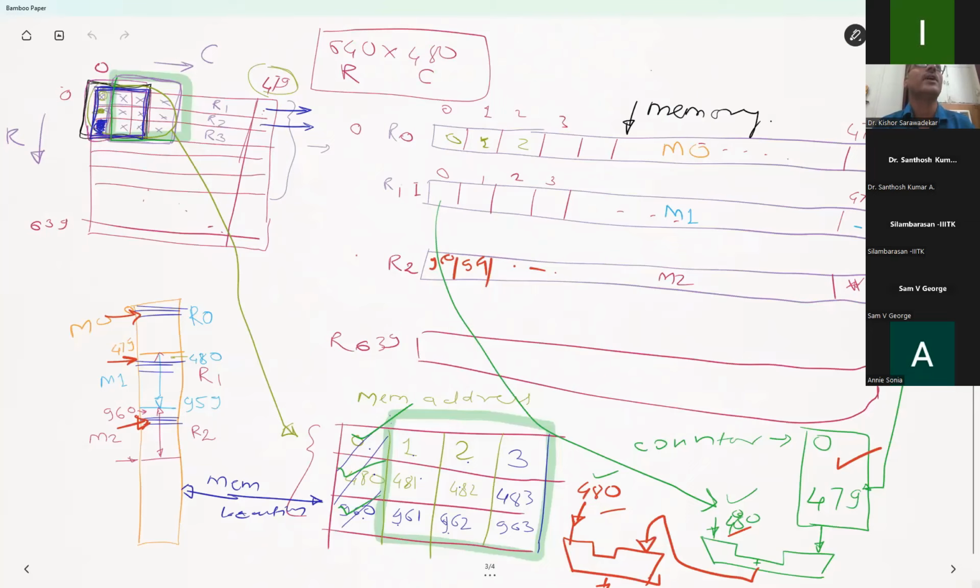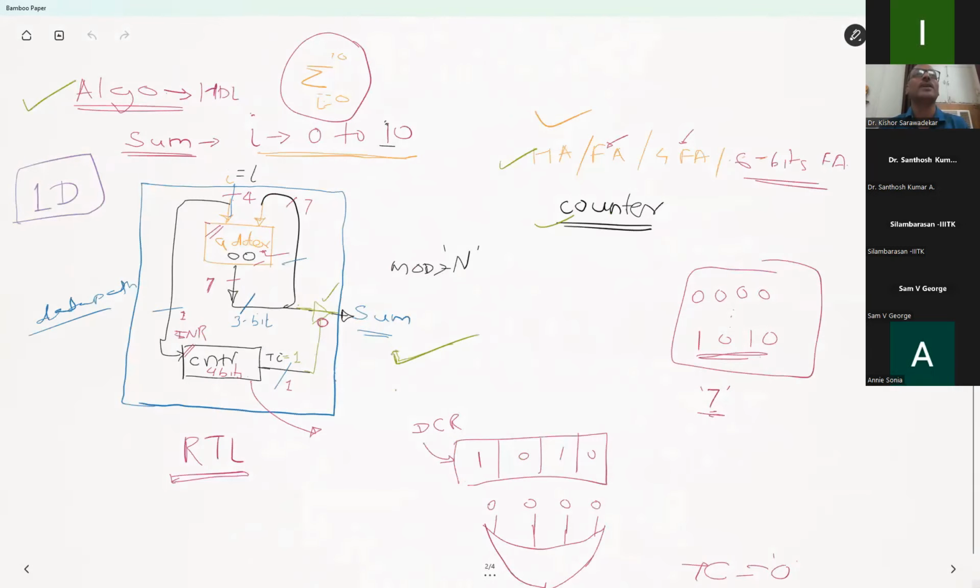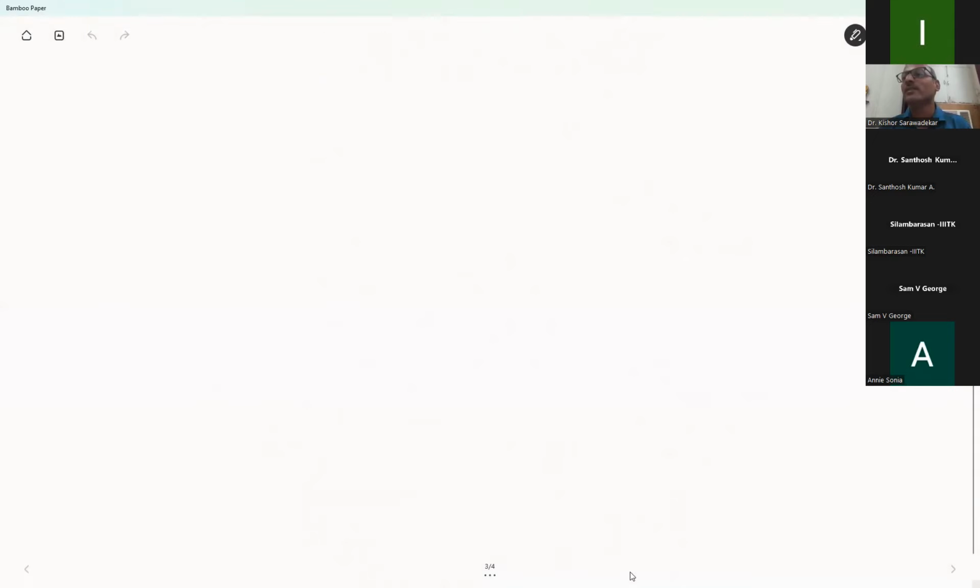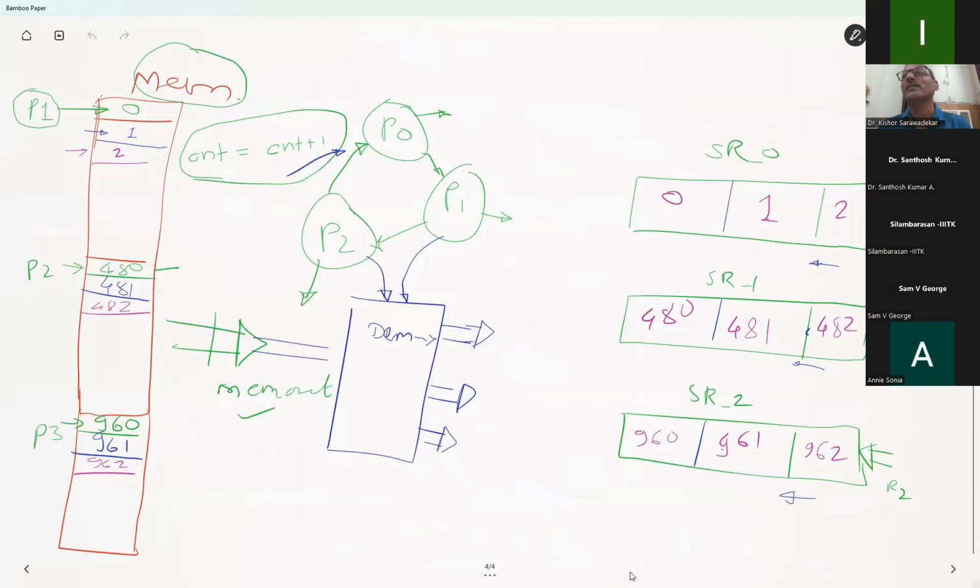So now on this kernel, you use this kind of adder. If you are interested in low pass filtering, so what should happen? You will do now summation of 9 pixels. And then you will write back the data to the center pixel. So for the center pixel, now you need to point at this particular location somehow, and write the updated value.